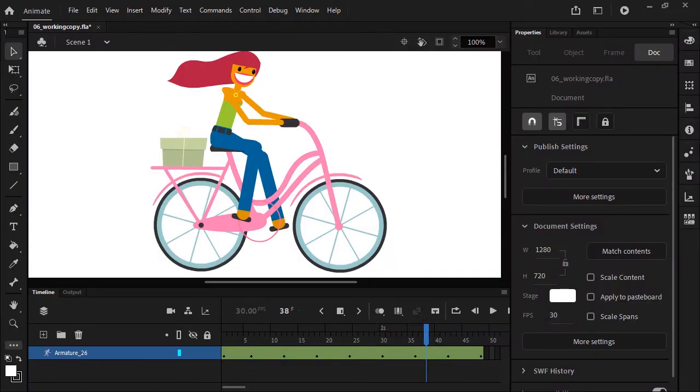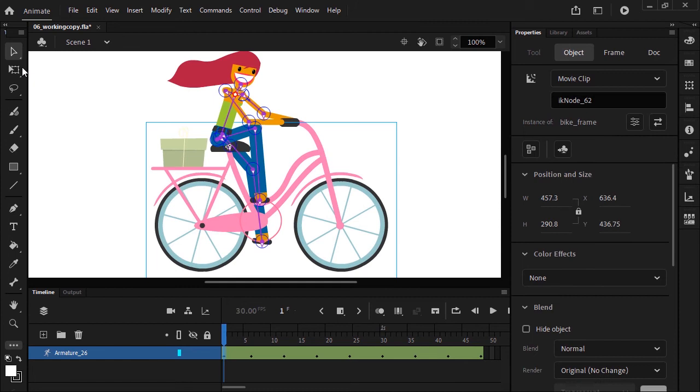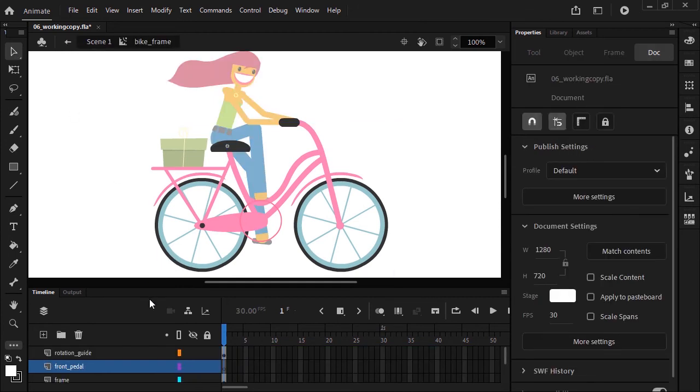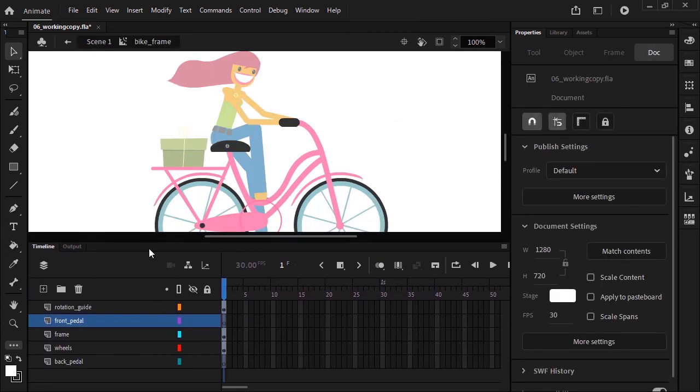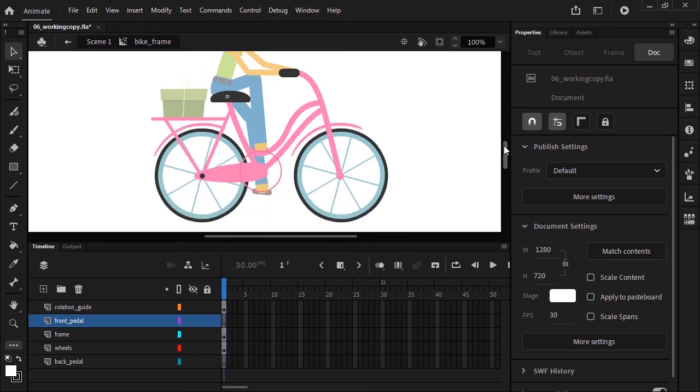Adding a nested animation of rotating wheels. Double-click the bicycle frame on the stage. You enter symbol editing mode for the bike frame movie clip symbol, but you're editing in place so you see the other graphics on the stage dimmed. Double-click the back wheel to drill down to the wheel turning movie clip symbol.